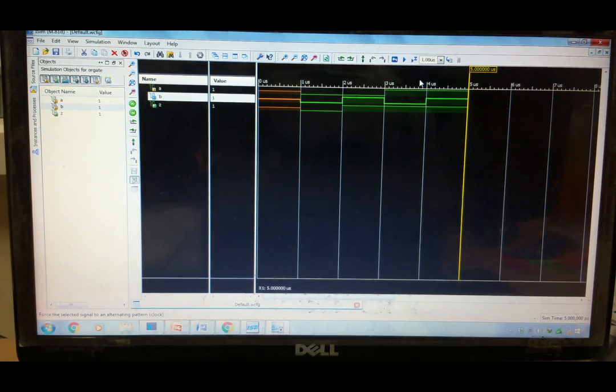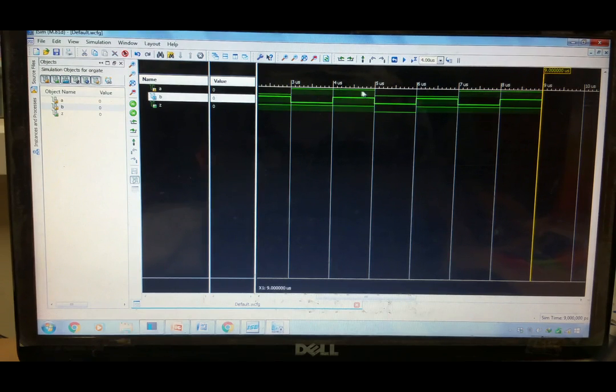So I can also change the run time here from 1 to 4 microsecond. Then I will select run for the time specified. So see, from 4 microsecond the simulation has run to 9 microsecond, from 5 to 9, sorry. So here all the 4 cases are visible, which earlier we were doing with 4 different force values. Similarly, this is the way you can give a clock to the inputs, and you can check the value at each instant of time by selecting this cursor.